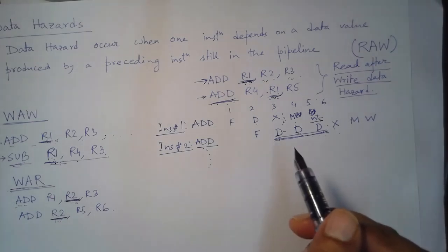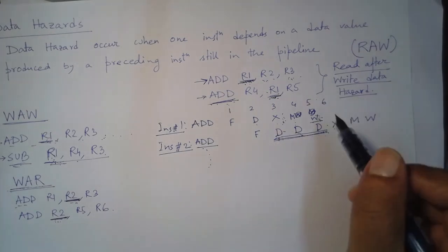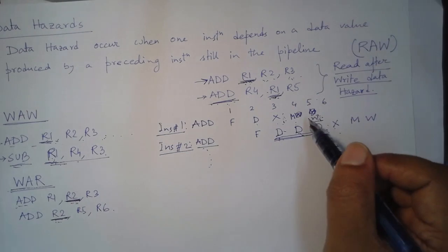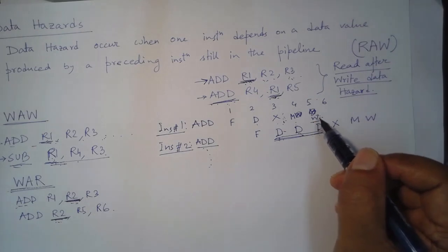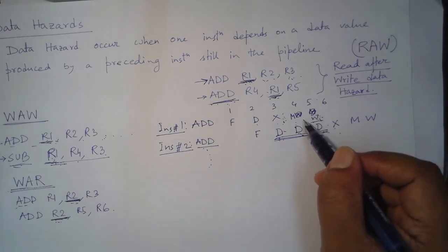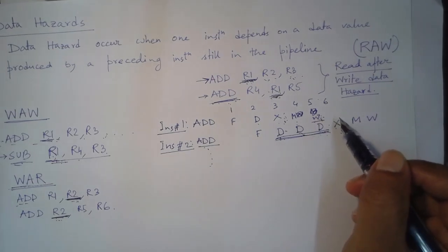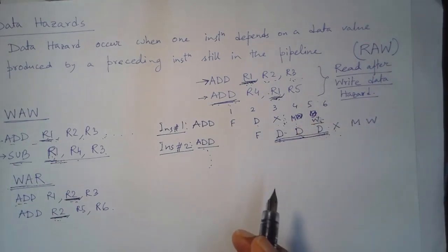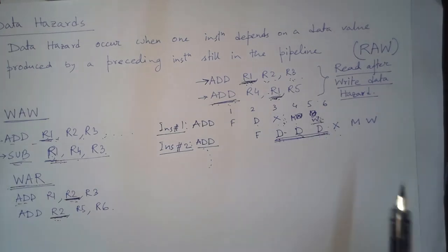So, this is one example where the value is getting updated in the execution stage, but there might be situations where, let us say for a load instruction, the load value will be available after the memory stage, so in those cases you can even think of bypassing after memory stage, so after write back stage, etc. So, basically we can add multiple forwarding paths. And obviously you want to forward the data from later to a previous stage. Okay.